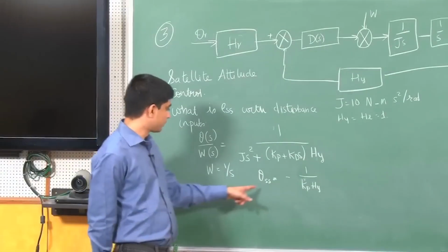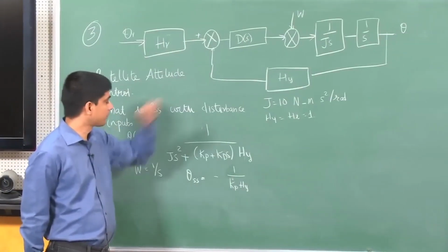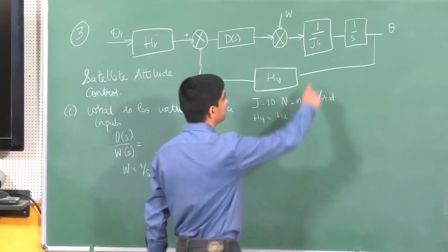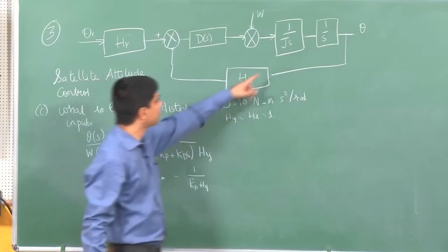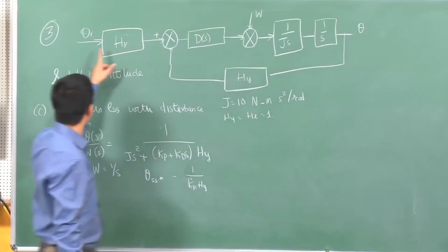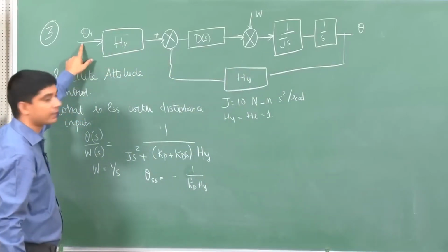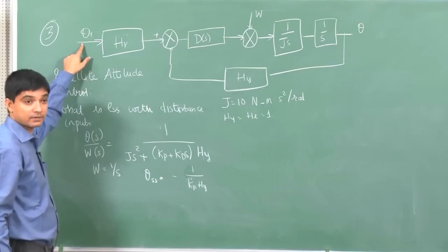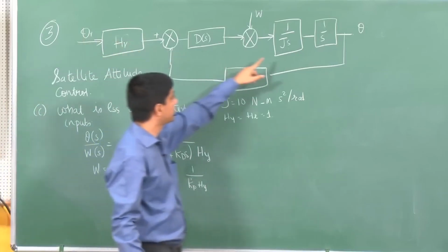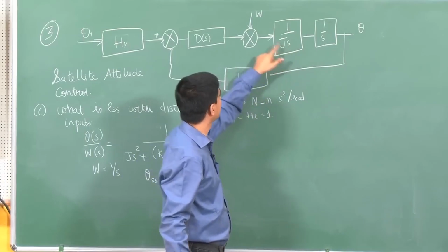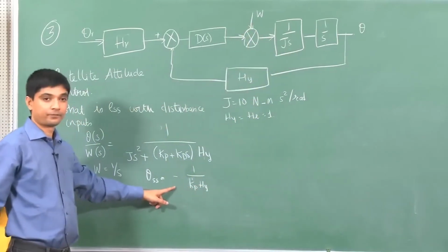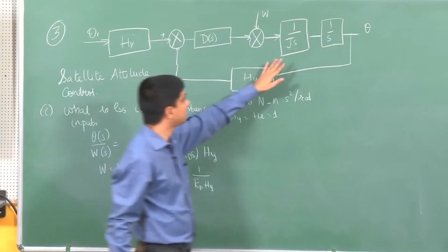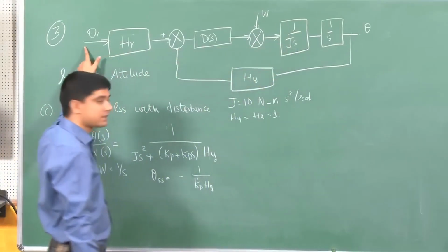Okay. So, what do we observe from here? Again, go back to the plant. The plant has 2 poles at the origin, and these 2 poles were okay to eliminate the steady state error when I was tracking a step reference. But these are not useful enough to reject disturbances, that is seen from here, and therefore a pole at the origin helps in the reference tracking.